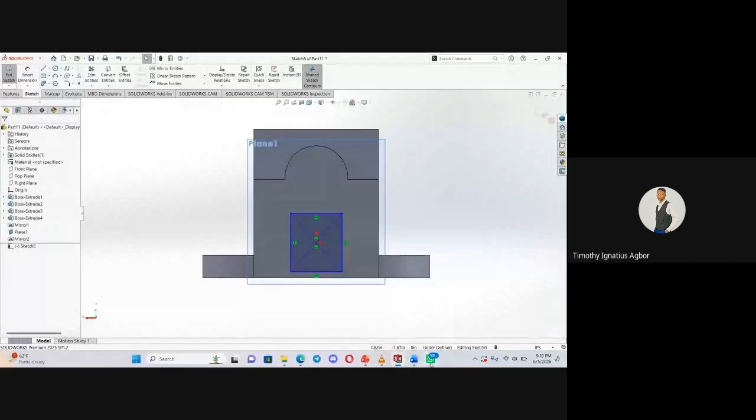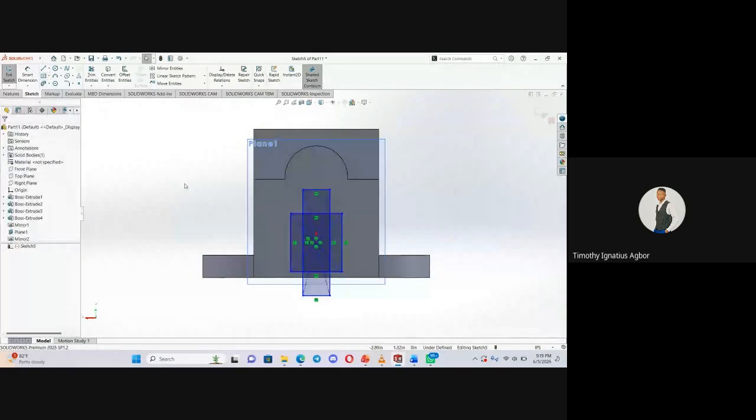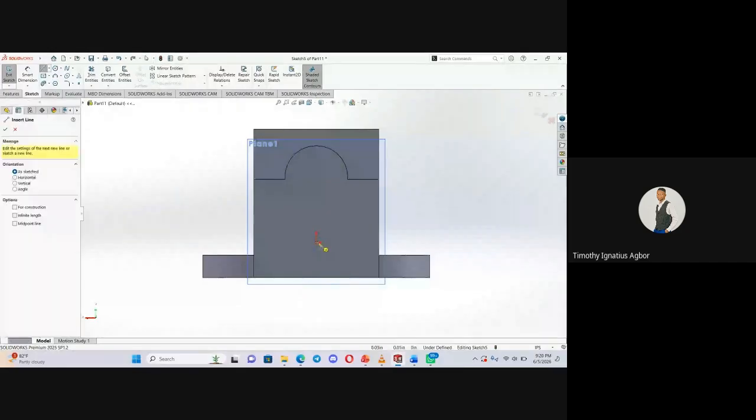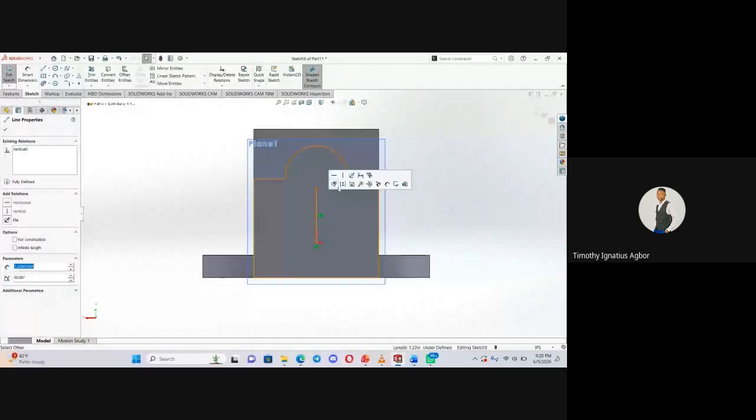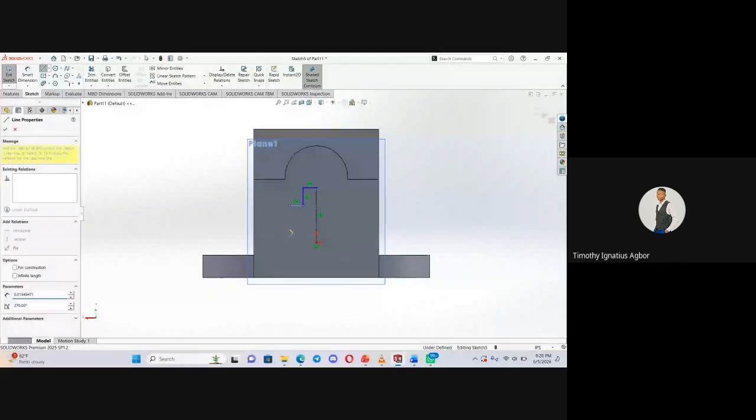If you look at this, there is also a center. We can use this or use this. This will be too bulky. So let's just create it ourselves. We create a center line. Make sure it is a construction line. We have a shape that looks like this, like this, like this. Cuts to the bottom here.